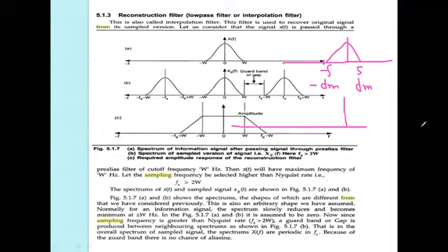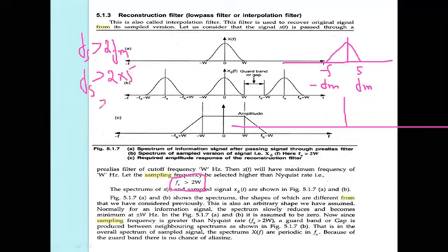Now, for the periodic signal with the band limit, we are taking the greater-than value. See, Fs is greater than 2 omega, or Fs is greater than 2 Fm. Okay, what is Fm? I assume Fm is 5, so 2 into 5 is 10. So Fs is greater than 10. I assume Fs is equal to 15. Let Fs be 15.